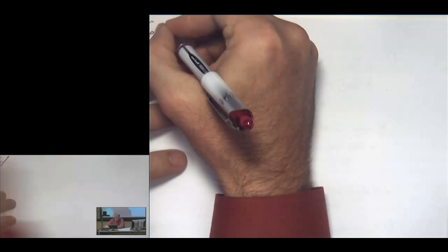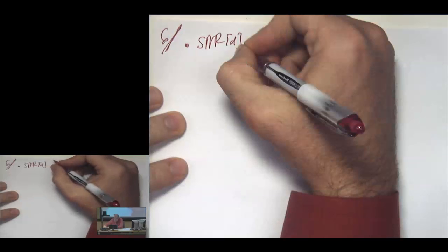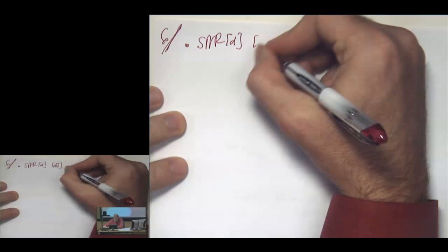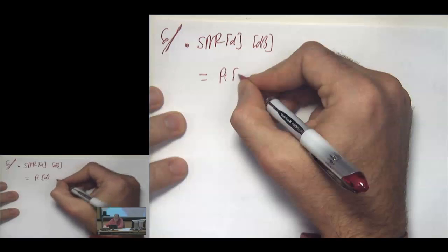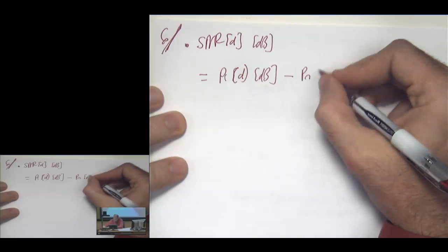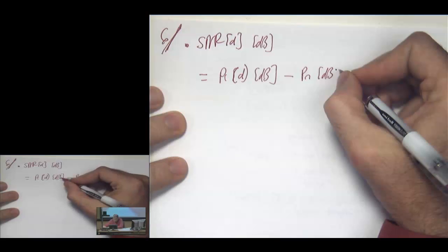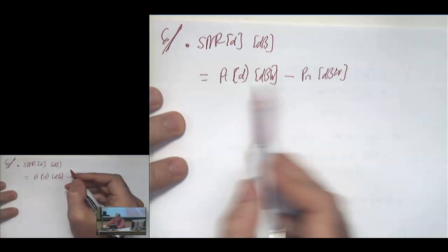Okay, so one quantity that we will want to compute is the SNR, because as we've already shown, in systems where there's additive white Gaussian noise, the performance is determined by the SNR. A quantity in particular that we'll want to compute is the average SNR as a function of distance. And so that average SNR, we can write this as a function of distance in dB as equal to the received power as a function of distance in dB minus the noise power using the same dB. So if this is dBW, we can put dBW here. Doesn't matter here. These can be dBm, this can be dBm. They have to be the same, though, because you have to cancel them out, because SNR is unitless.